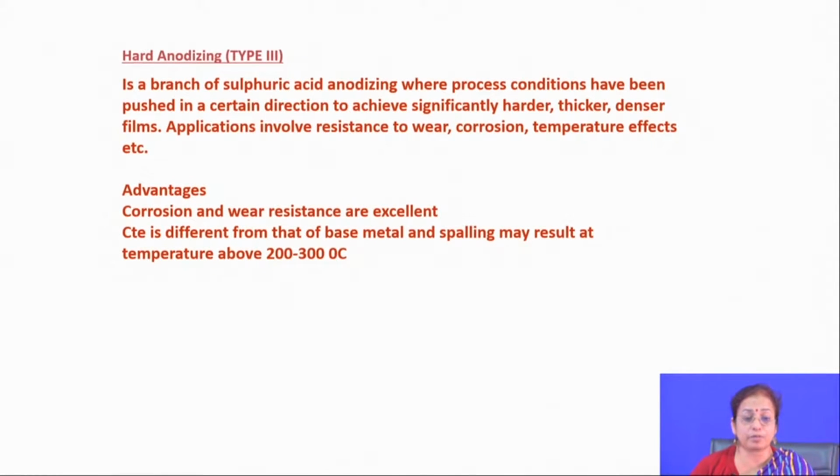The basic problem of anodizing is that the film thickness is not as high as is desired. The step in anodizing is that initially there is formation of oxide scale, and then because of nucleation and growth of the oxides, as soon as the whole coverage of the surface is there, the kinetics of the oxidation stops; it becomes very sluggish. So, usually 1 to 4 micron is the maximum thickness which can be achieved.